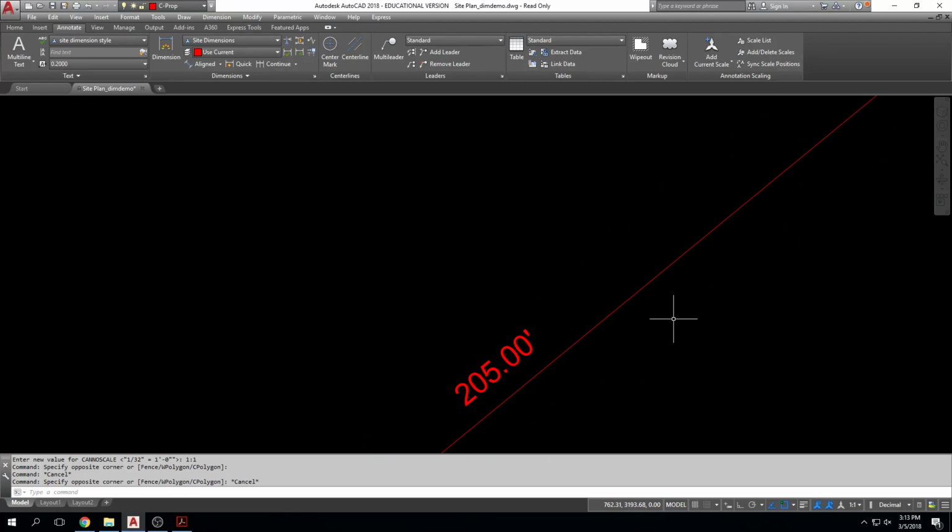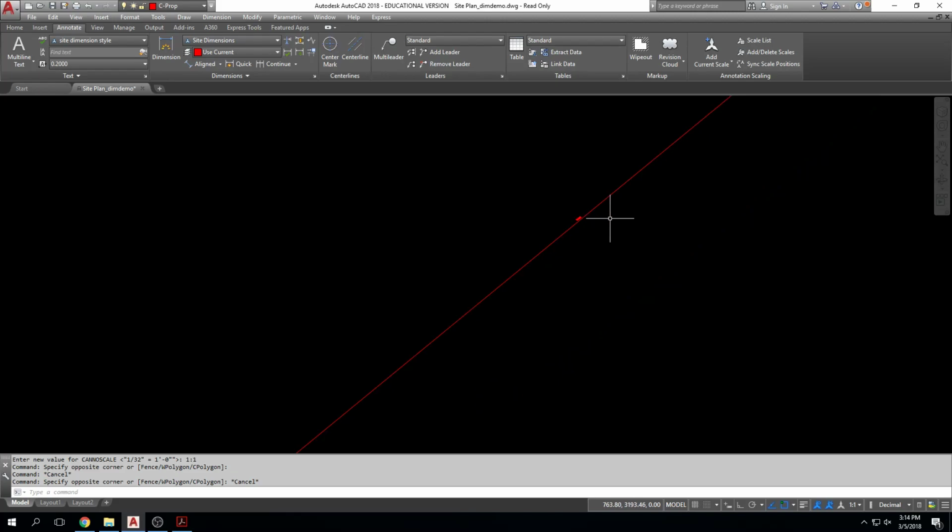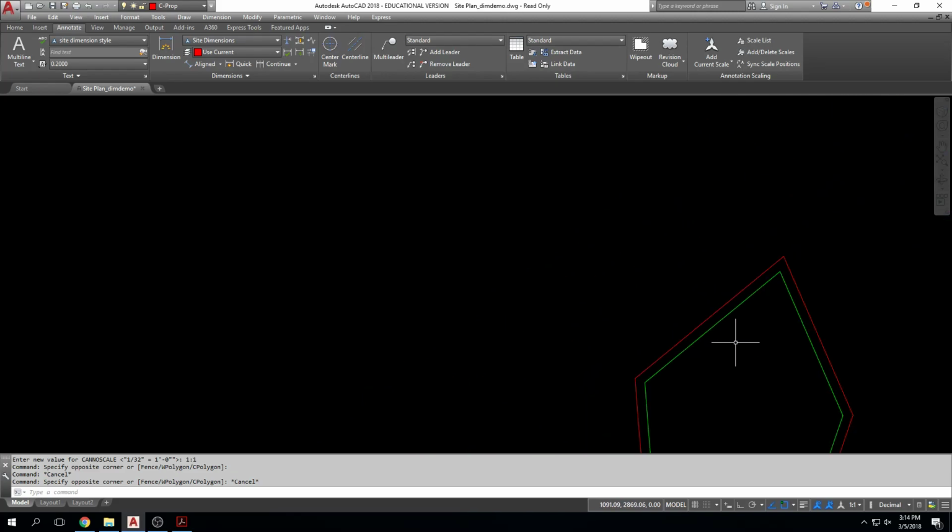Just tiny. What is happening there is it's anticipating you printing this at 1 to 1 scale, which means that little piece of text would be 3/32 of an inch tall, next to something gigantic like a site plan. So the scale is not allowing that text to be seen.